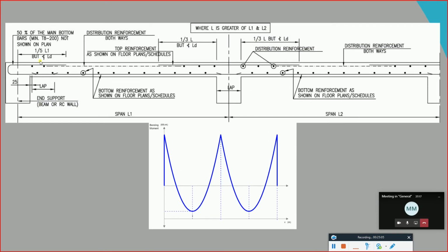The same thing goes here. Okay? So bottom reinforcement goes from the beginning till the end. When I have a support or a top bending moment, then we can go here and supply reinforcement for the top. Okay. When it comes to the sides, we have 1/5 of L. When it comes to the center, we are taking 1/3 of L and then 1/3 of L.